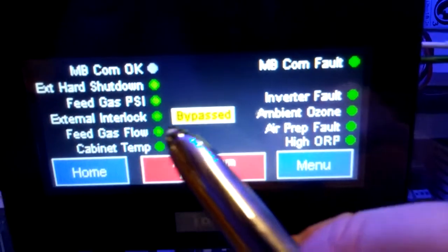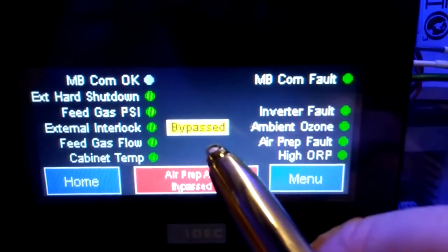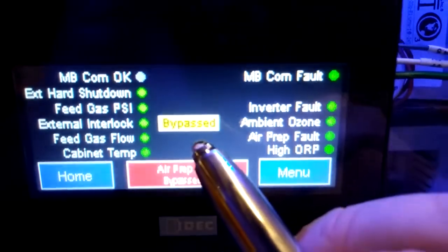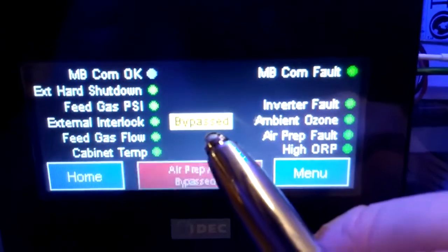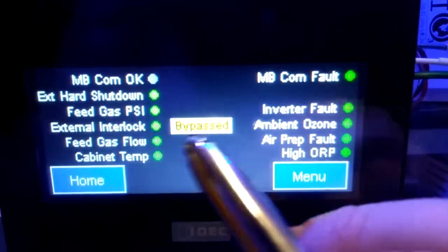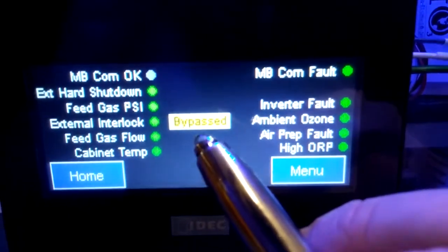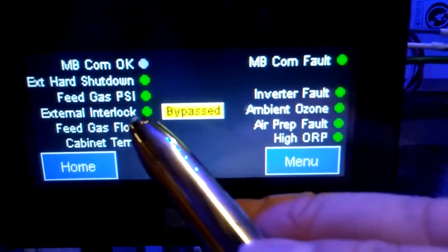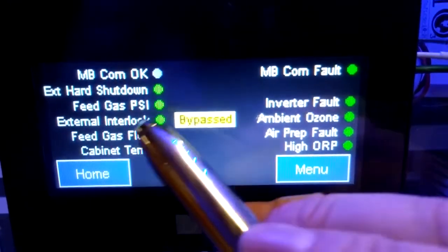The external interlock is basically a remote run command. If the system is being controlled by a remote SCADA system or something and the technician is trying to work on the generator locally, he may need to temporarily bypass the external interlock to allow him to run the system without tracking down an operator to activate the system remotely. So in the factory screen, if the external interlock has been bypassed, that's when you'll see this indicator next to the external interlock tag.